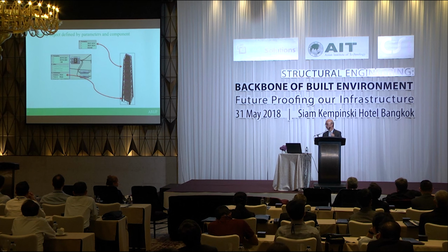But every time you change the final product you're looking for, you have to change the male die and also the female die. So a company at that time developed this kind of parametric technology that links the relationship between your final product, the male die, and the female die. That means all you need to do is change the product you're looking for, and then the computer will automatically generate the male die and the female die for you. This is one of the early applications of parametric technologies.